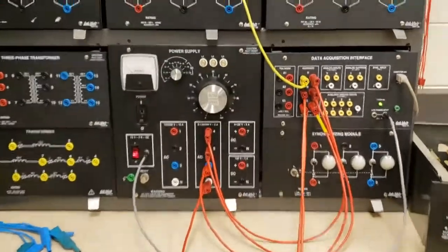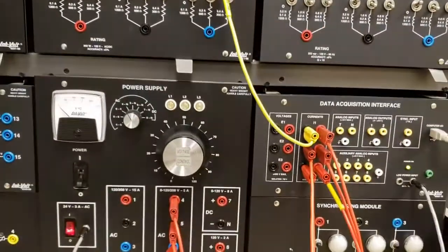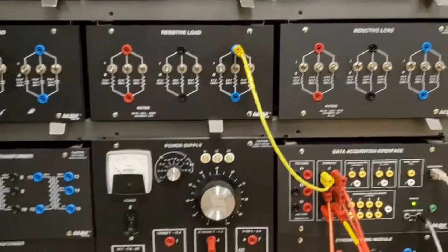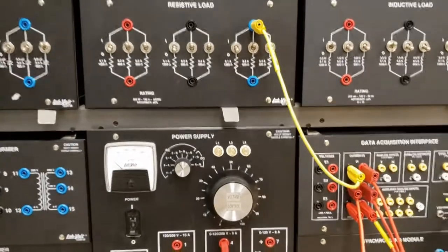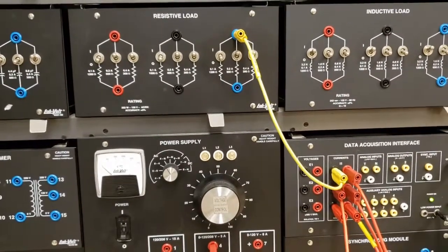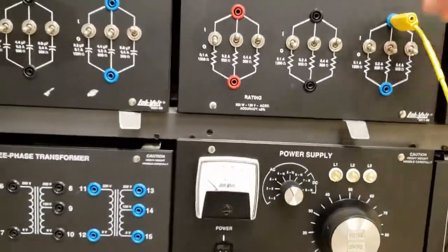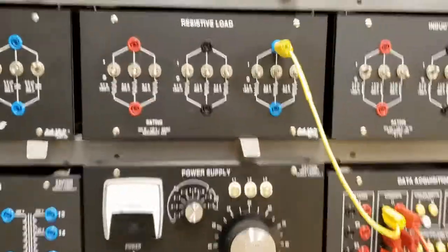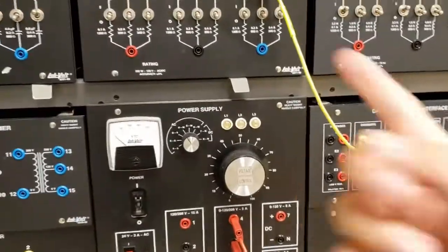Okay, so I'm going to film this rewiring. I had it initially connected as a Y configured load. I'm going to film how you do it into a delta load because it's actually a little bit hard to visualize how you connect a delta configured load. I remember the previous semesters, people had a lot of trouble doing that. So I'm going to go ahead. I'm just going to switch those off. And the power supply is off and everything. I'm going to show you how you do that.